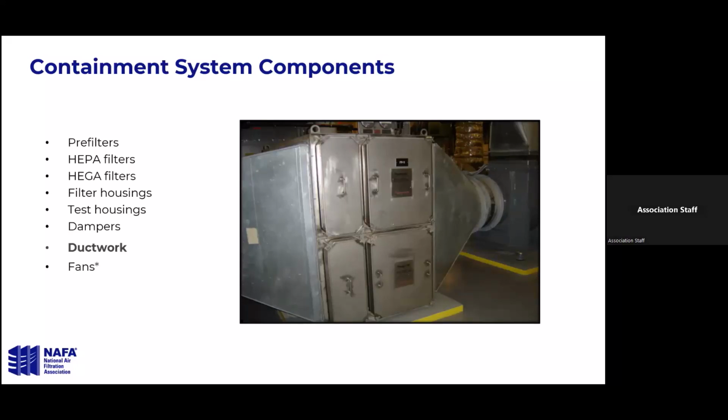I've got ductwork here in bold. Generally, the housing manufacturers aren't supplying the ductwork for these, but something you have to keep in mind, especially if you're working with somebody designing a system, is you can have the best containment housing in the world, but if you're not attaching ductwork of the same quality, then you're going to have leaks in that ductwork. So the ductwork has to be high quality as well to match the performance of the housing.